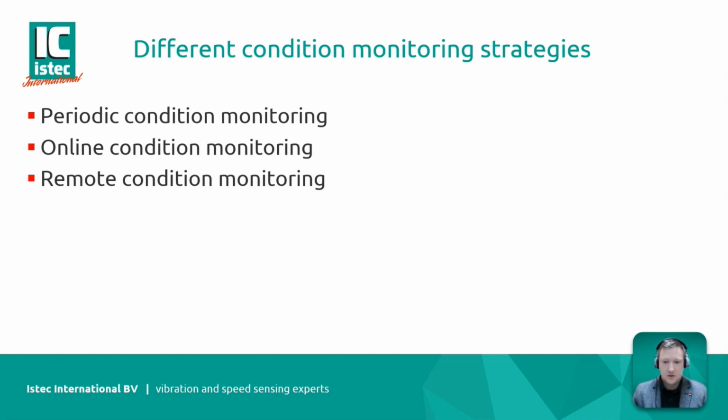And periodic is when a condition monitoring specialist will travel to site periodically. So every quarter, every half a year, every week, whatever is determined, goes to site with this data collector, collects data, and analyzes it.